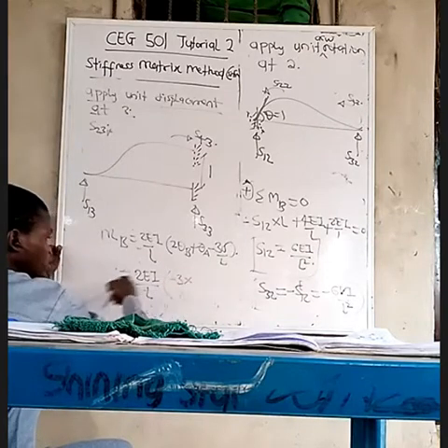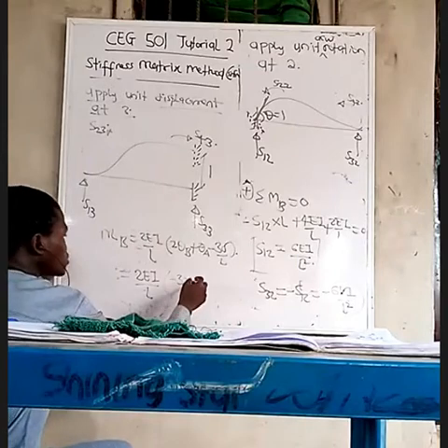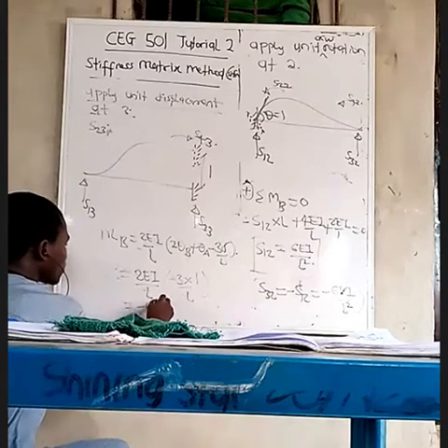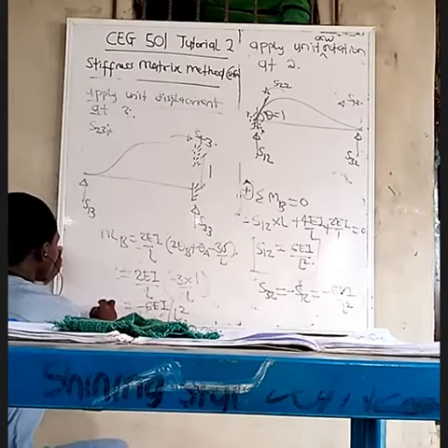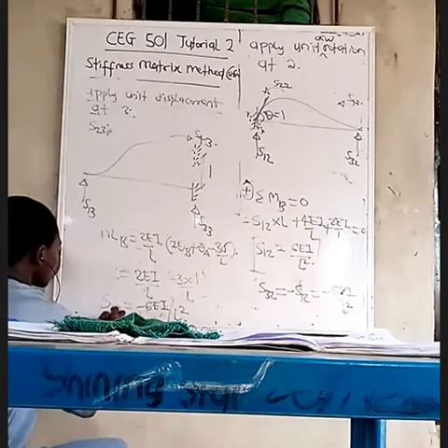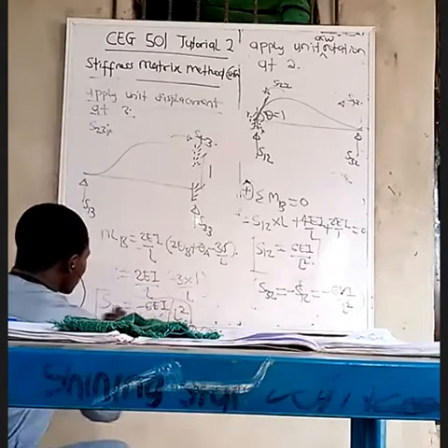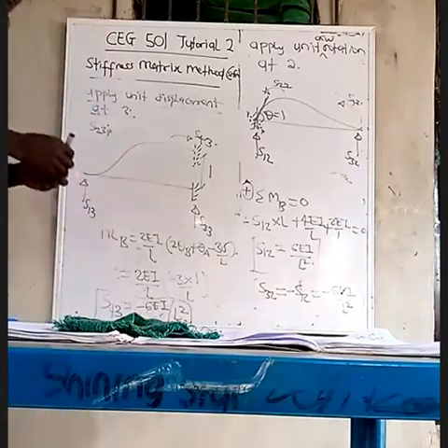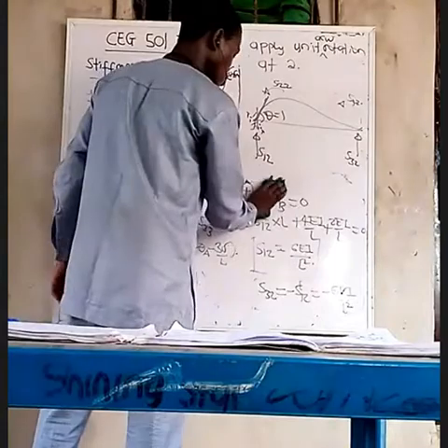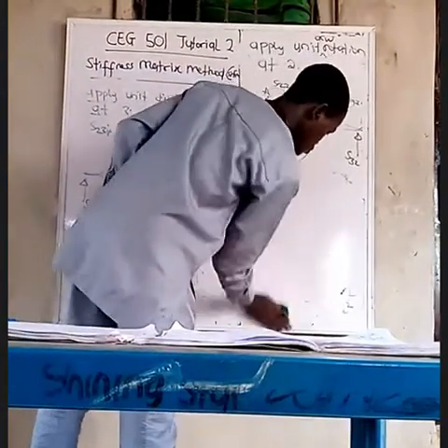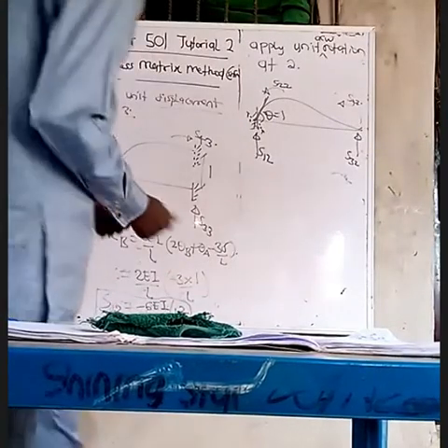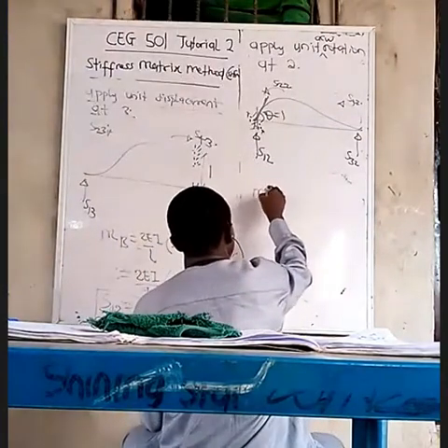So we are going to have a negative moment here, minus 3 times 1 over L. I drew the diagram, so I believe you can still check that. So that becomes minus 6EI over L squared. That's S43. I'm going to clean this off now. S43. So we can calculate S23 as well.